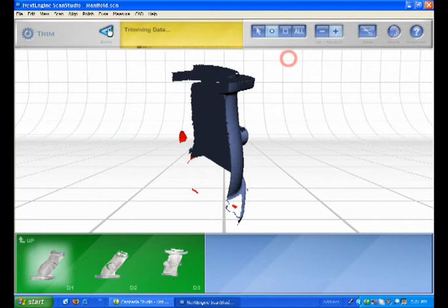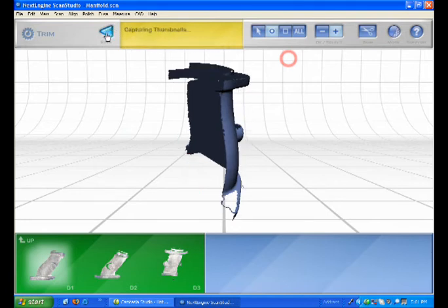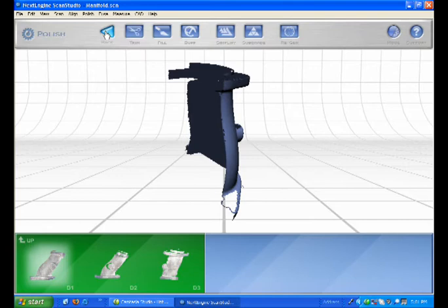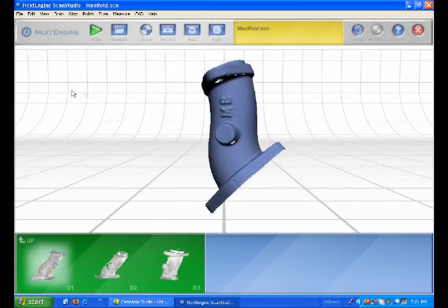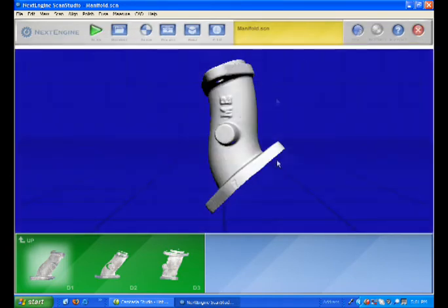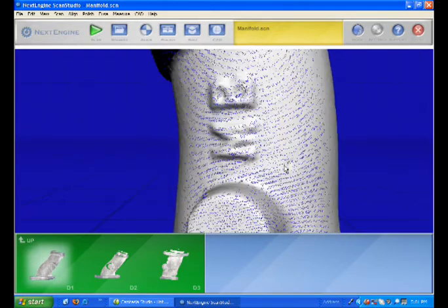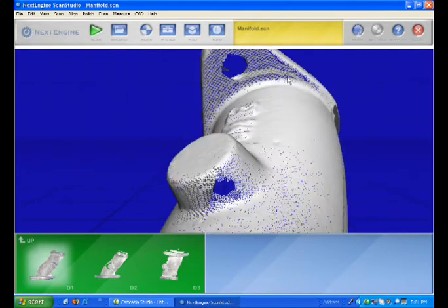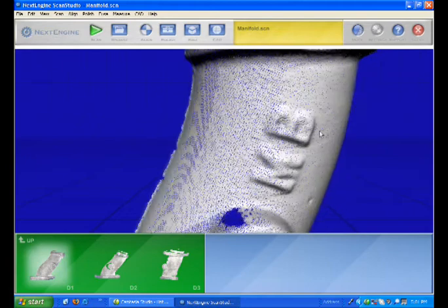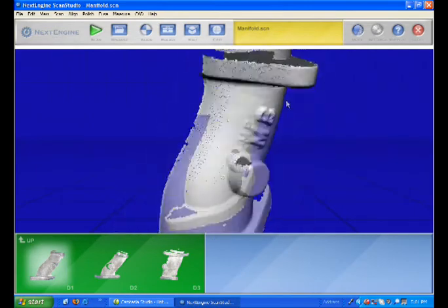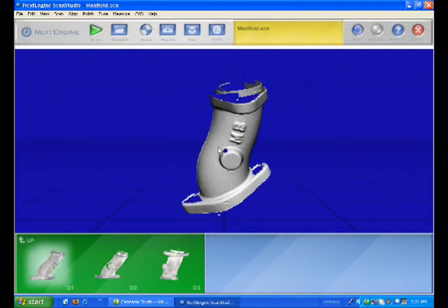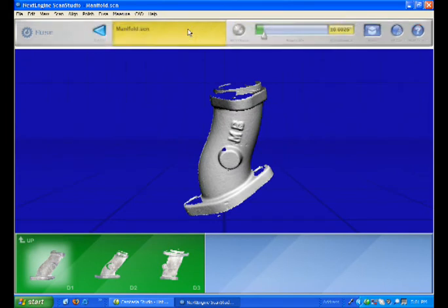The last step we're going to do now is basically fuse the scans together. And remember that the fuse is going to do 3 things. We got a few areas there. If you look, there's a few occlusions that we missed, so what it's going to do is merge the scans together. It's going to hole fill and do intelligent decimation.